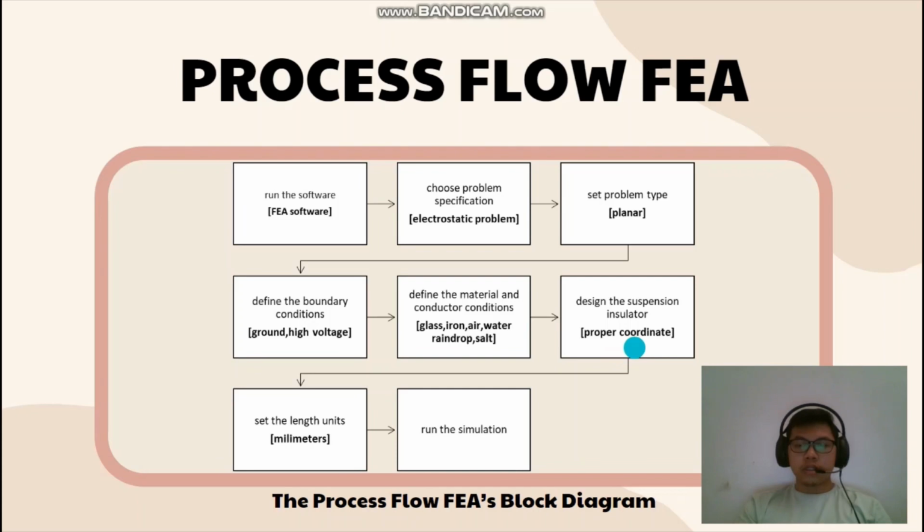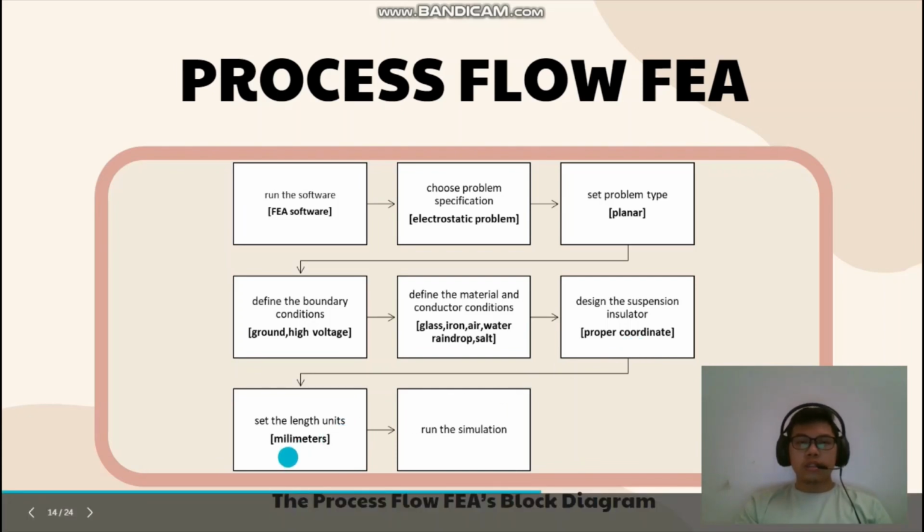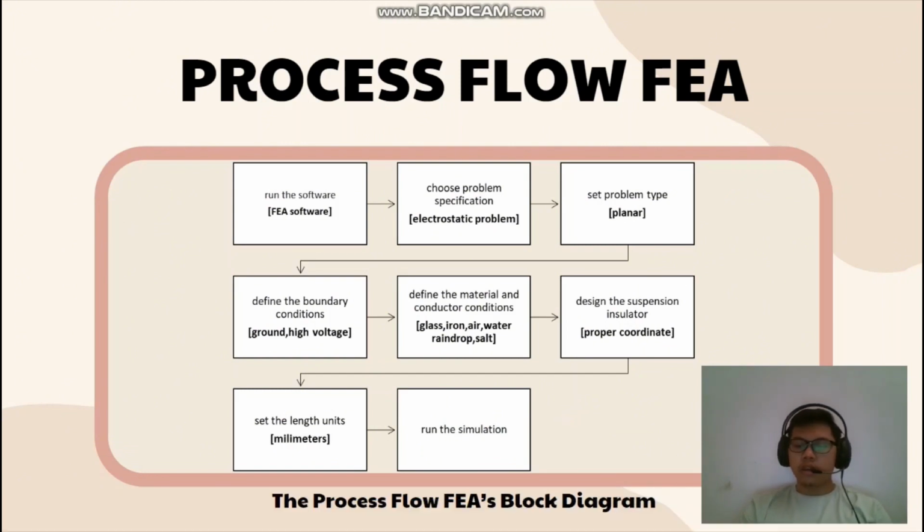Design the suspension insulator into the proper coordinate. And then we set the length units into millimeters. And finally, we will run the simulation. So this is the block diagram for the process flow of FEA.